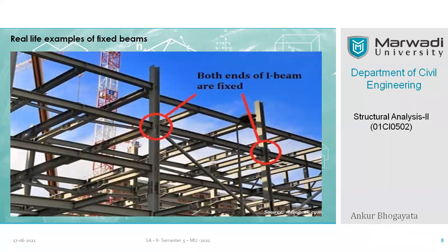One is vertical and the second is horizontal, if the support is a hinge support. But if you employ a fixed support there, you have an additional reaction in terms of reacting moments. That means your beam, as well as your entire structure or even the entire frame, is capable of resisting and reacting against moments.